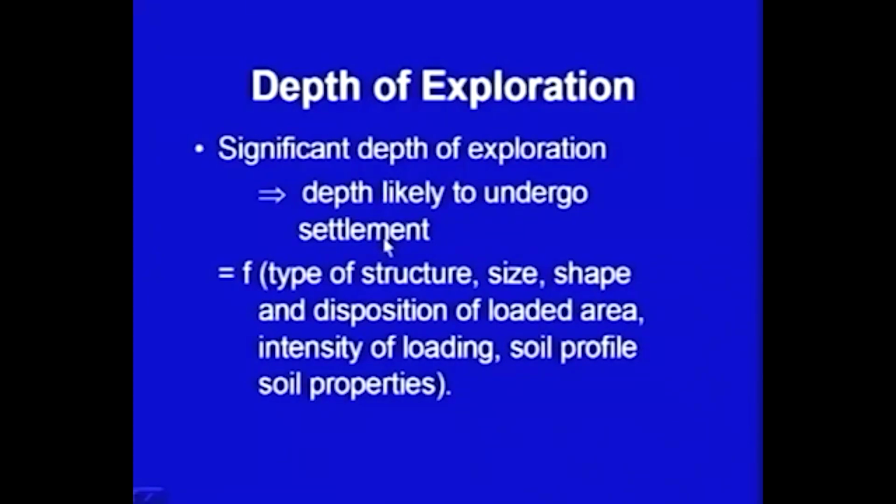It means we should know about the strata below the foundation which is causing the settlement, and it should be a function of the type of the structure. It will depend on the size and shape of the footing, the disposition of the loaded area, intensity of loading, soil profile, and soil properties. On all these things, this will be depending.